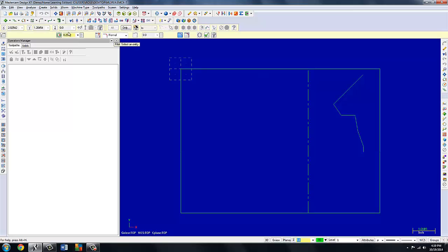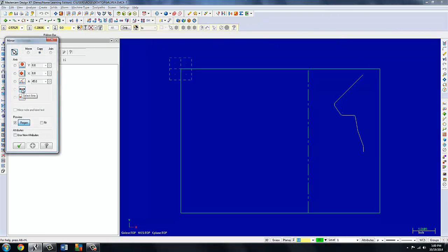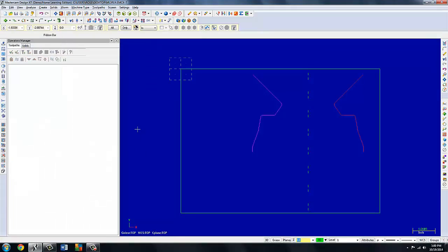So I go to fillet, 1.25, got one here and here, got one here and here. I can accept those, and I've got a 0.0625 fillet right here. And that is my profile contour ready for mirror imaging. So I go to X-Form, Mirror, slide a box around all of that and selection. I want to select a line, that one, and there we have it. X out of that, clear colors. Now we've got something to start preparing our handle geometry for.